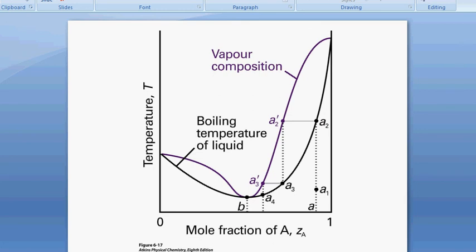So some of the examples of azeotropes are, for example, hydrochloric acid and water. These form an azeotrope, 80% mass by water. This boils at 108.6 degrees C. When you have an 80% water, 20% HCl mixture, you can't separate it. So it's an azeotrope. Now this is the property. Ethanol water. So remember, 80% mass water boils at 108.6 degrees C.